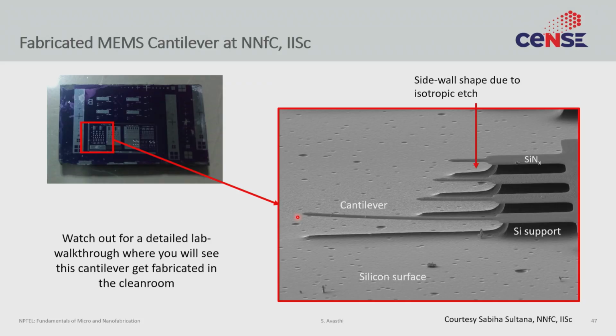There are also adhesion effects. When you are doing etching, this is all dry etch, so there is no liquid involved, but if you are doing wet etching, you can often have surface tension type effects, which can also pull a cantilever towards the surface or away from the surface. Finally, you see some pitting damage during etching. So we are doing dry etching, so we are sort of bombarding the surface a little bit, and that can cause some amount of damage. For MEMS devices, this damage is not very severe, so it's not a big issue.